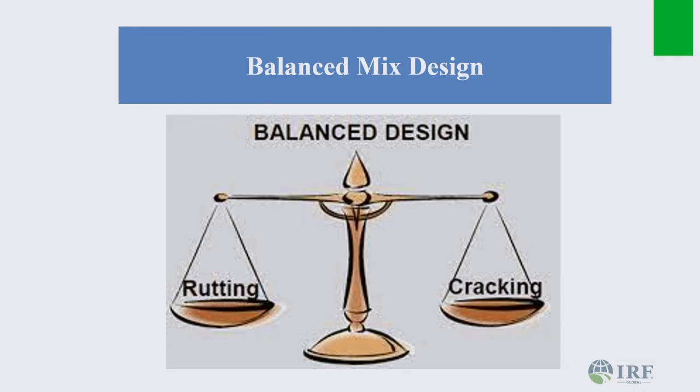Yeah. So bottom up is what? It's mainly when it's possible that your base has a problem, and that is causing the rutting. So we call that what? Consolidation rutting.